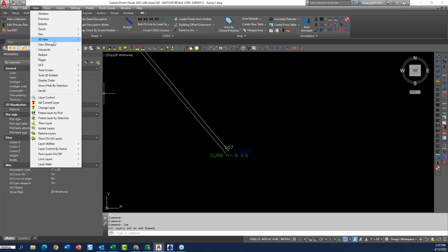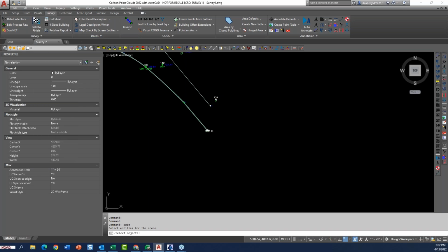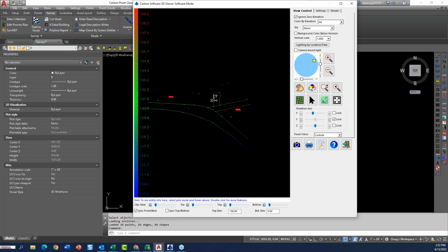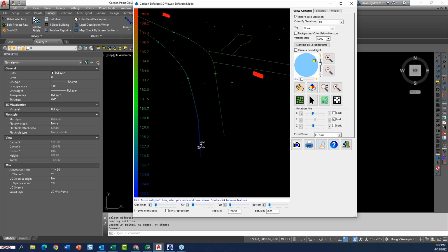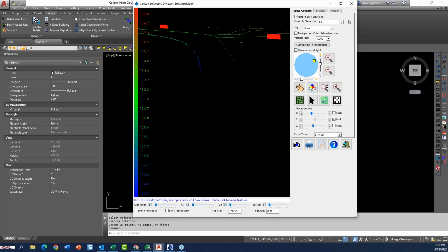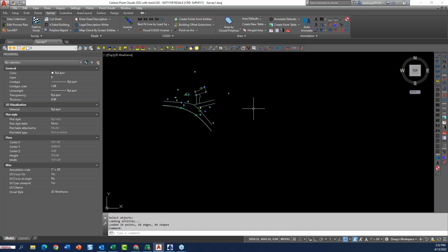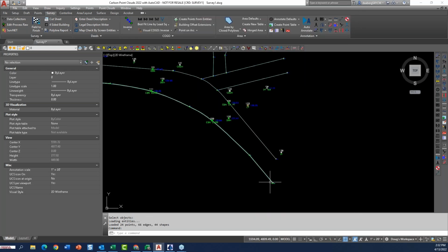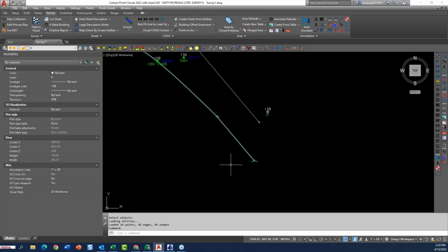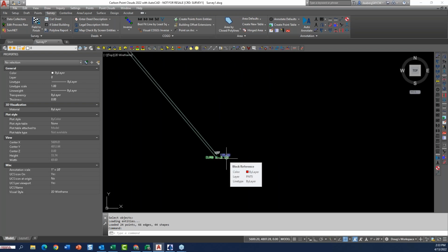If you remember the command cube, I just type it at the command line. But if you look at drawing viewer, I can actually window this all in, and you can see my site in 3D. Don't really need that colored. And you can see that line is offset vertically and horizontally. So when I go to contour this now, I've already got both break lines in there. Again, this only had to be coded on the very first shot.